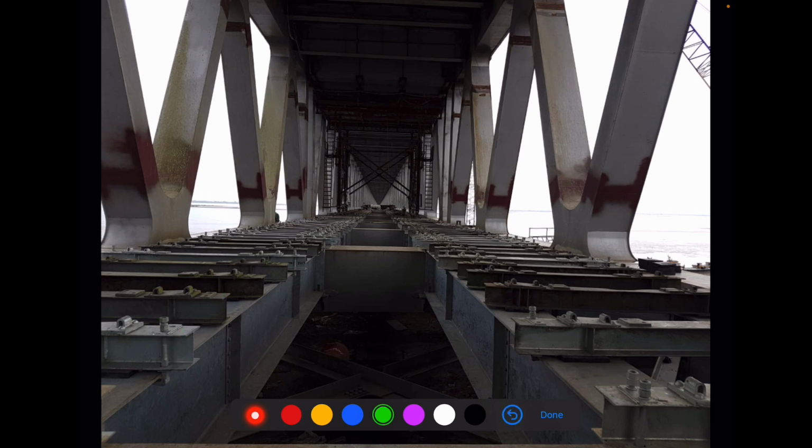Yeah. In this particular case, you can easily see this is the cross girder, these are stringers, and H-beam sleepers of I section have been provided. These are holding down hook bolts basically. These are inserts over which rails can be fixed with the help of elastic rail clips. And yes, you can see these rubber pads also.